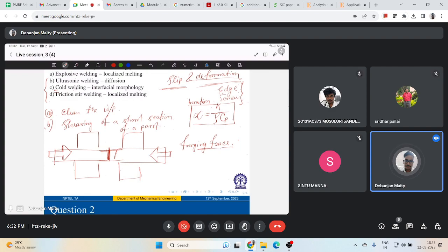Otherwise, it cannot be soft and cannot be deformed. That's why in cold welding, as this is happening at room temperature, mostly people use ductile material without excessive work hardening. There is a total absence of heating source. You can join dissimilar metals also, but the most important thing in cold welding is surface preparation. You have to prepare your surface very carefully.